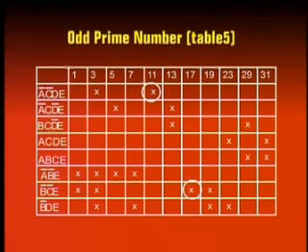In each cell, an X is marked indicating that the prime implicant listed in the left column covers the minterm mentioned in the top row. Thus, the prime implicant A bar, C bar, D covers the minterms 1 and 5. In other words, minterms 1 and 5 all have the product terms A bar, C bar, D. The table 5 can be directly implemented from table 3 and 4.